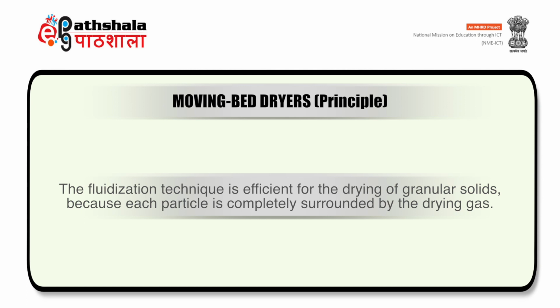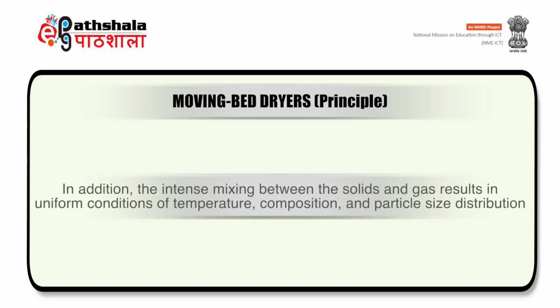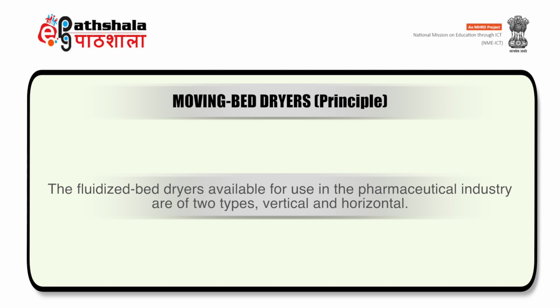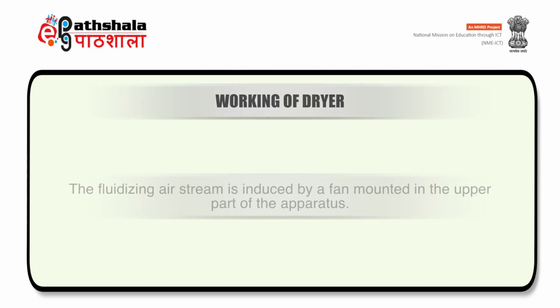The fluidization technique is efficient for the drying of granular solids because each particle is completely surrounded by the drying gas. In addition, the intense mixing between solid and gas results in uniform conditions of temperature, composition and particle size distribution. The fluidized bed dryers available for use in the pharmaceutical industry are of two types, vertical and horizontal. The fluidizing air stream is induced by a fan mounted in the upper part of the apparatus.